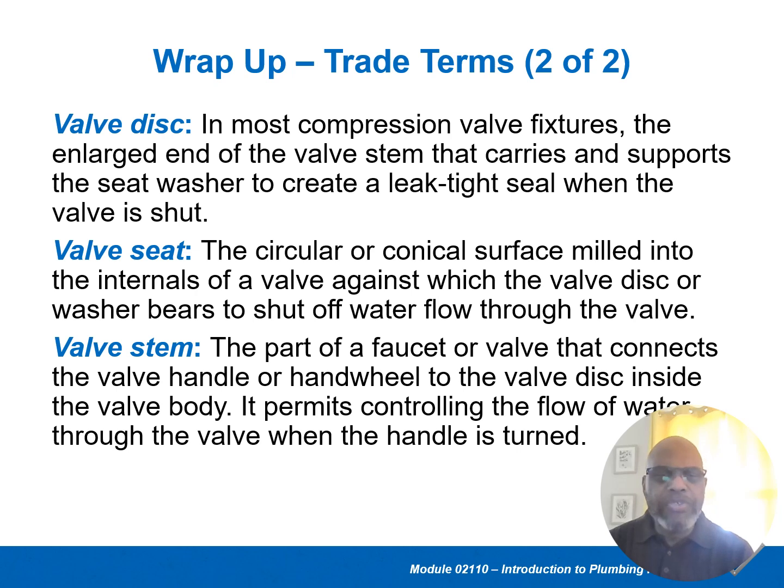So basically, it is the base of that stem that holds that washer in place. If that ever cracks or goes bad, usually it's time to replace the whole faucet. Usually these type of faucets last for years, and you can still buy replacement parts for old faucets because it was so common back in the day to repair them. And old houses that still have them, it can be rebuilt to bring it back to new standards.